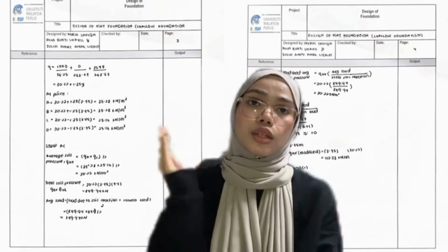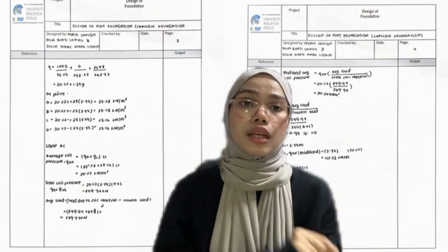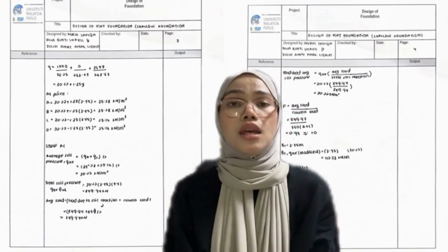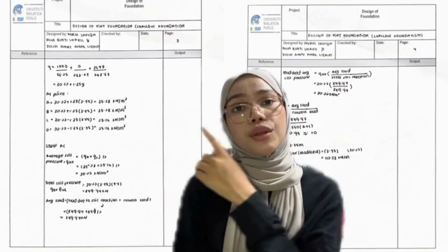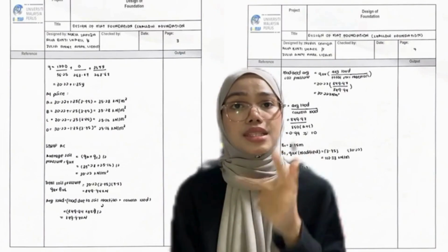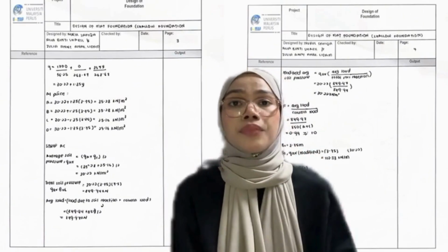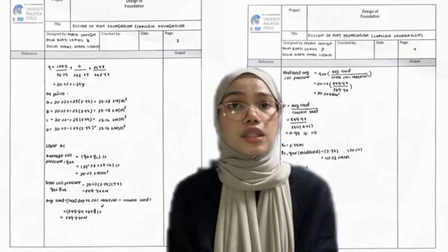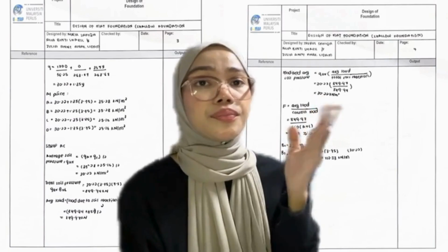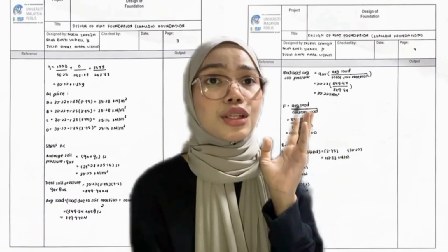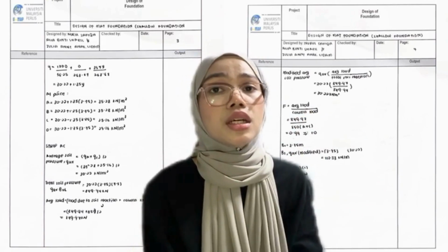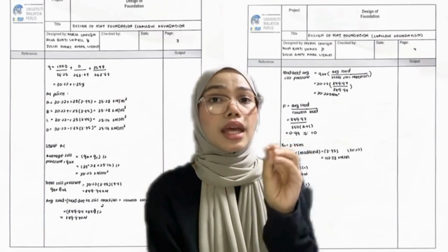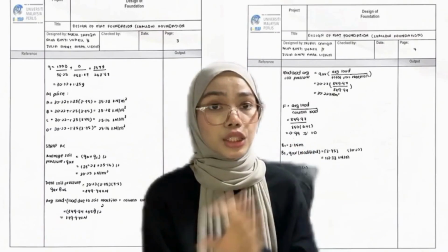After that we need to calculate Q. The answer that we got for Q is 30.22 plus 1.35y. We need to calculate Q at every point, which is A, B, C, and D. For strip AC, we calculate the average soil pressure and then the total soil pressure. After we got the value, we calculate the average load and modified average soil pressure, and then we divide the average load by the column load to get F. Then we calculate QA and QC.